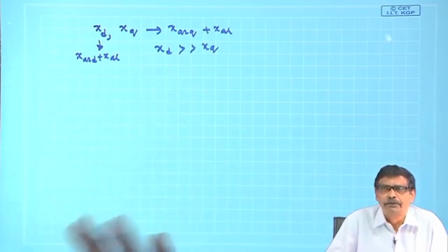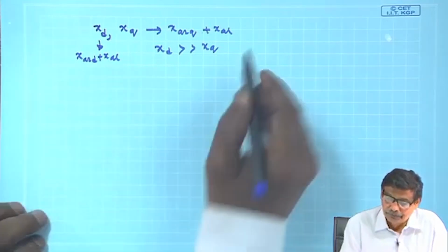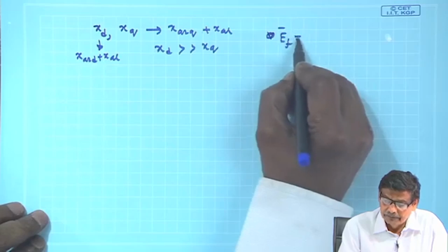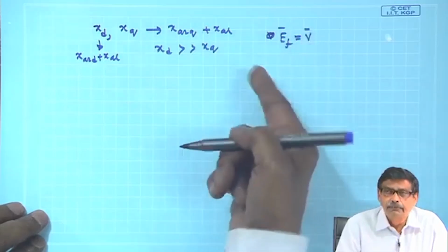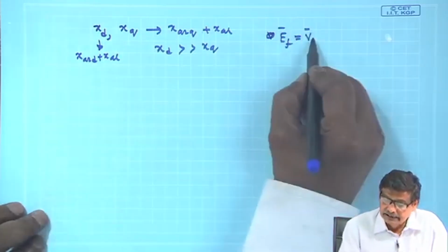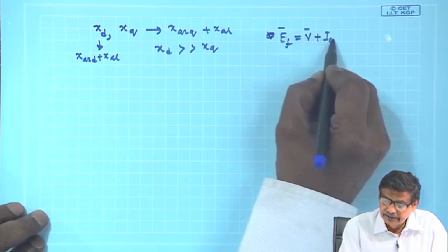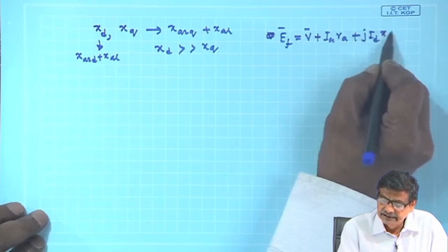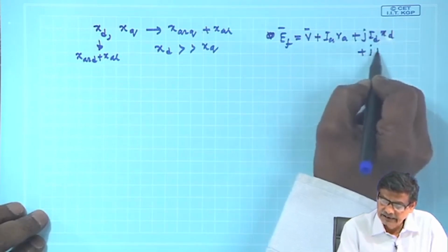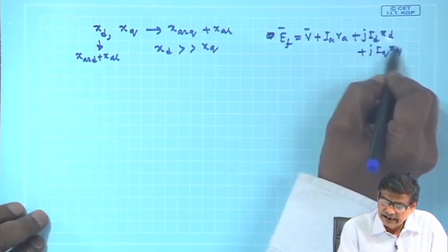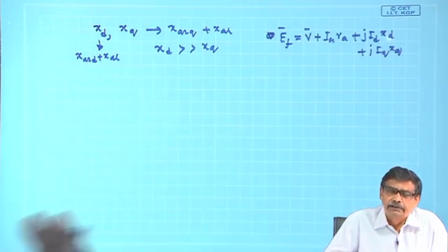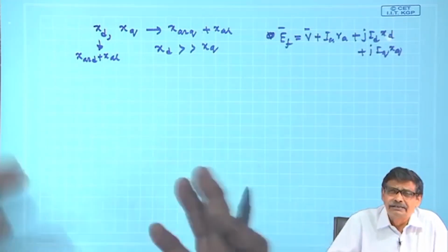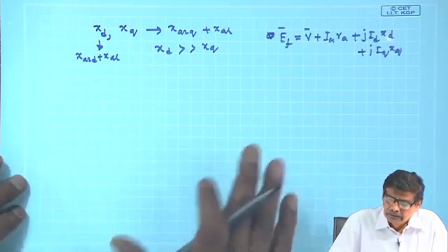No, it is not possible; separately you have to do it. In generator mode, this point must be very carefully handled: Ef is equal to V plus IA RA plus j ID XD plus j IQ XQ, and ID and IQ will be different because the armature current is broken up into different components. So, they cannot be represented in series or in parallel.